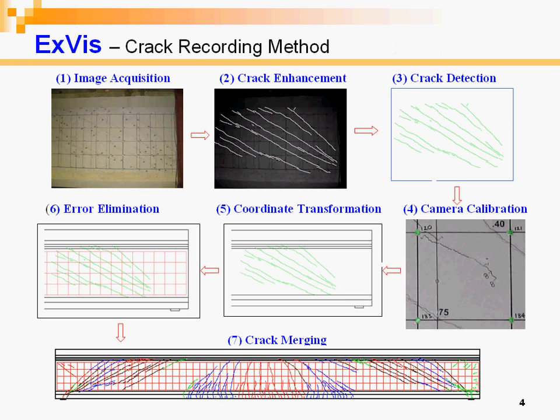The crack locations that were shown in the demonstration were obtained from high-resolution photographs using principles of close-range digital photogrammetry. By using reference coordinate information contained within each photograph, it was possible to transform the position of each crack from image coordinates to girder coordinates to an accuracy of about 1/8 of an inch of the measured location of the crack.